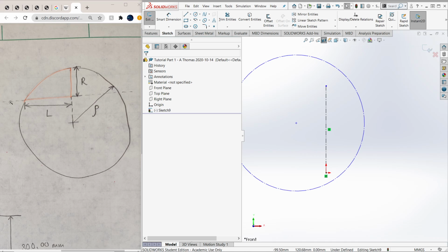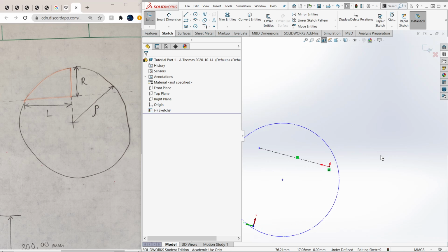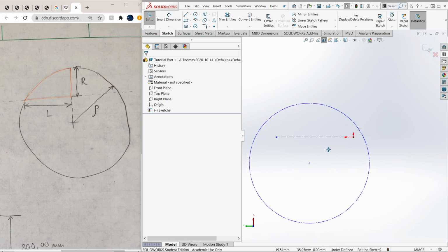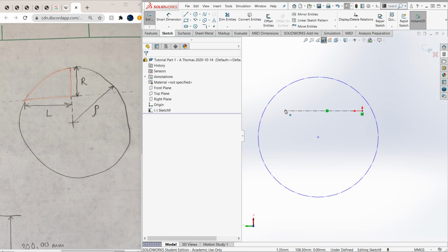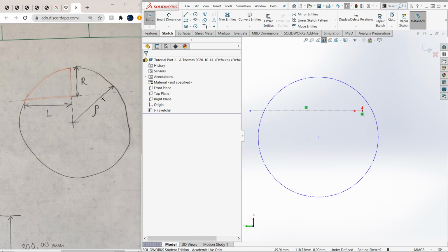If we look at this center line, I'm wondering if I want to rotate the screen. That might be useful. I remember how to do that. If you do Alt and the arrow keys, you can rotate the screen front and back. So I'm going to Control, middle mouse click, and pan over. I'm going to basically recreate that little sketch. Move this line over a bit so it looks a bit more similar.